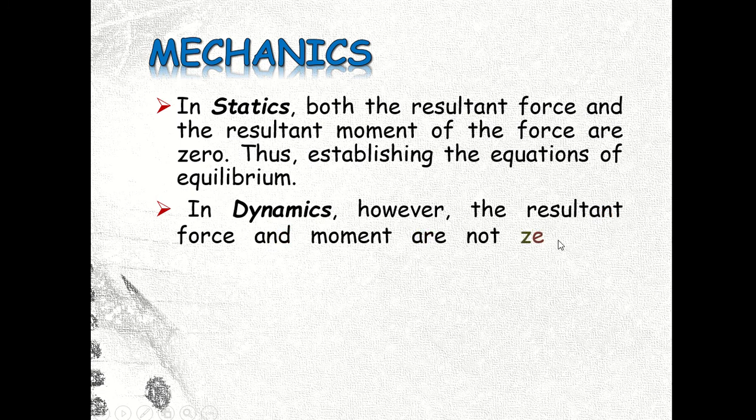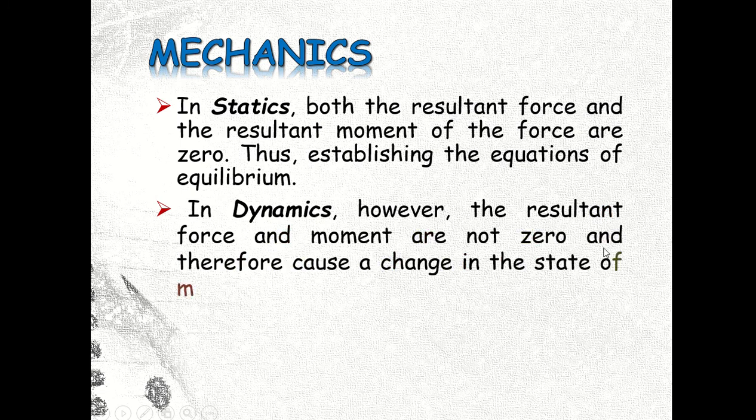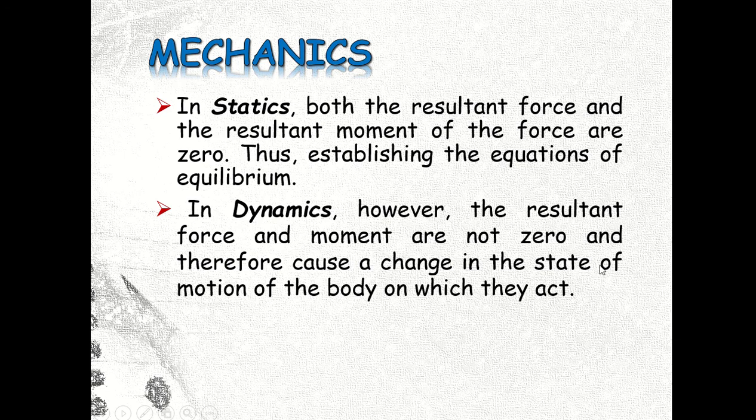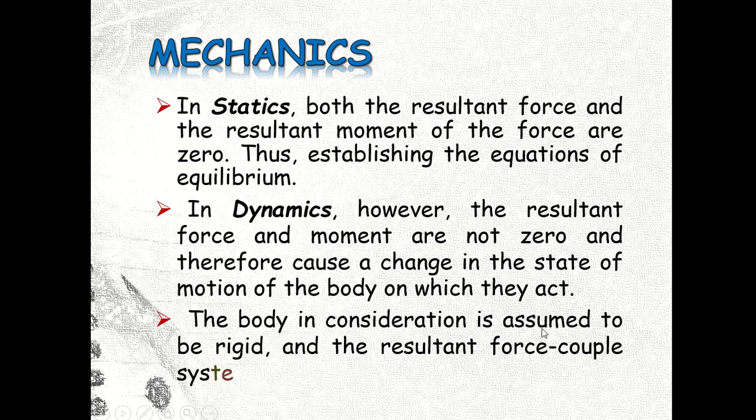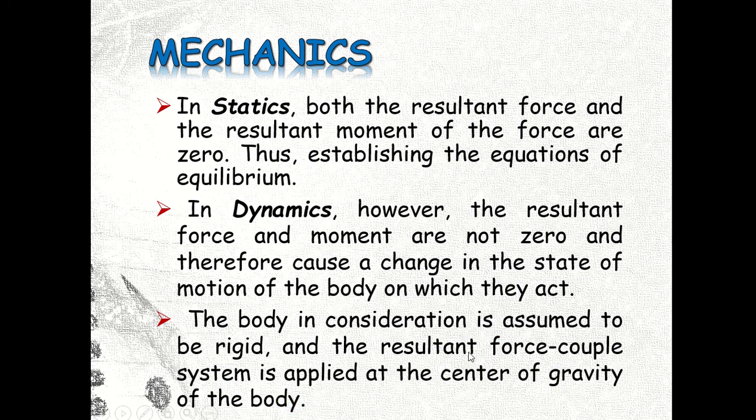In dynamics, however, the resultant force and moment are not zero, and therefore cause a change in the state of motion of the body on which they act. So the body in consideration is assumed to be rigid, and the resultant force couple system is applied at the center of gravity of the body.